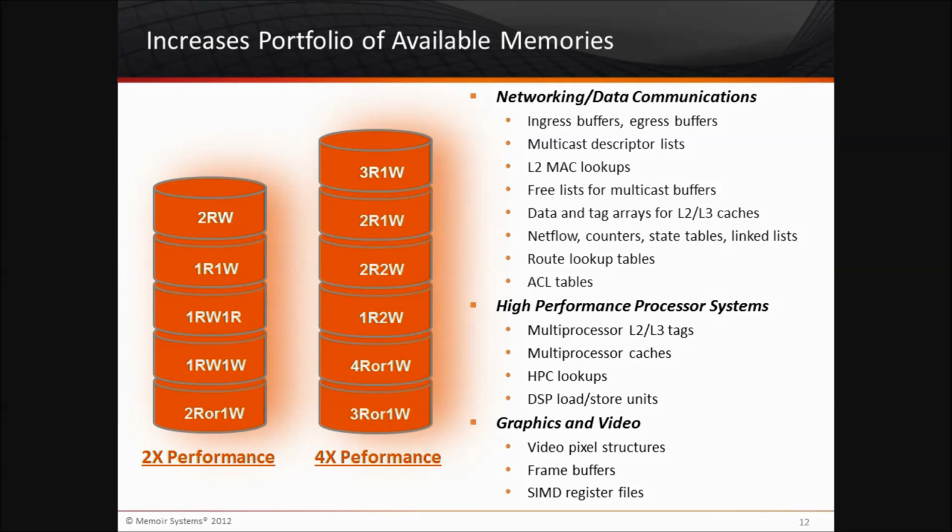You can, of course, use it for other applications, such as L2, L3 tracks in microprocessor caches, graphics and video pixel structures, where, for example, 1 port here is bidirectional, that's 1 RW, and the other port here is read-only, depending on what your application does.